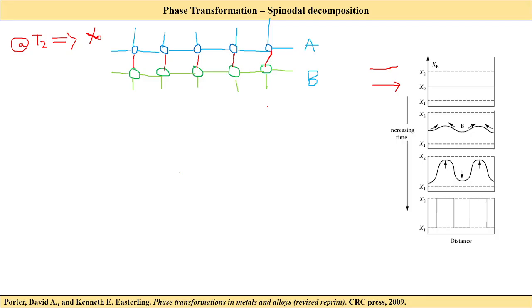Now, if my lattice parameter is a bit different, then there needs to be a distortion, and there needs to be accommodation of a strain energy, right? And if we do not have any large change in lattice parameter, for example 2.01 to 2.011, so a very small distortion, then that can be easily accommodated.